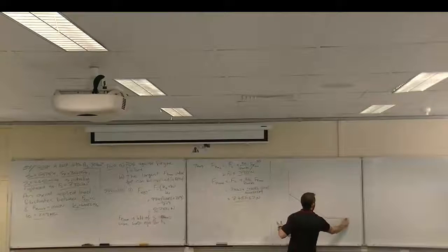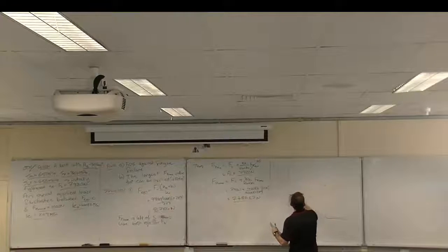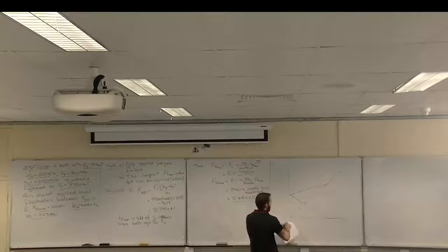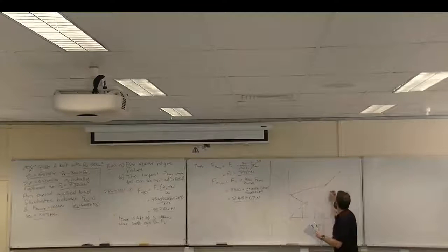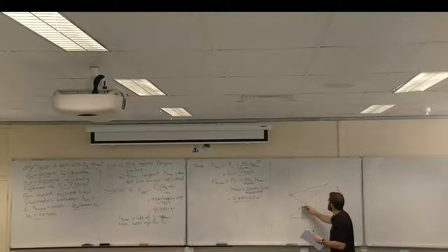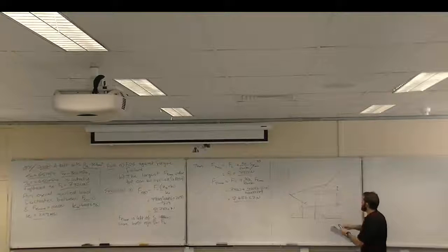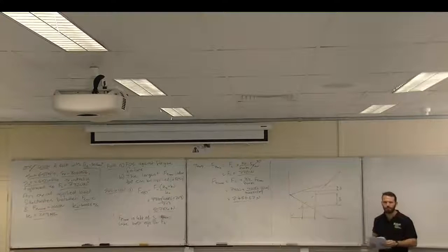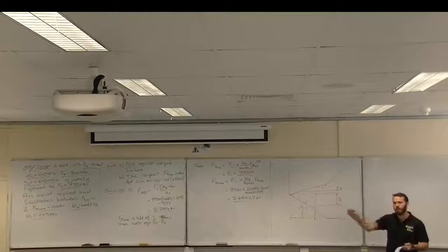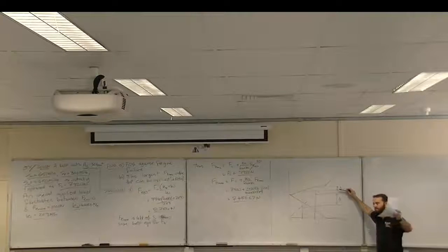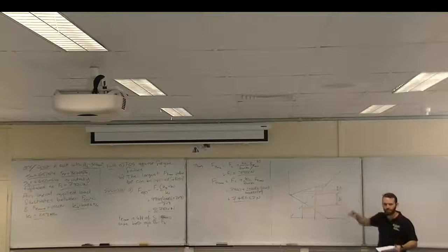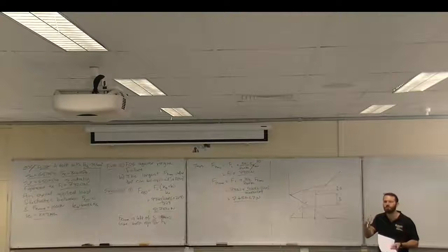Alright, so if we're fluctuating between 2 points, we just project those up. And so the change when you have an initial tension, compared to the change when you have no tension, is that. Yeah? And so by having that pre-tension there, not only are you having all of those other advantages based on the separation, the plate friction, and all that, but in terms of fatigue resistance, you're decreasing the amplitude. Now, you're increasing the mean stress, but you are decreasing that amplitude. So that's where that trade-off comes, and there is an advantage from a fatigue resistance standpoint as well.